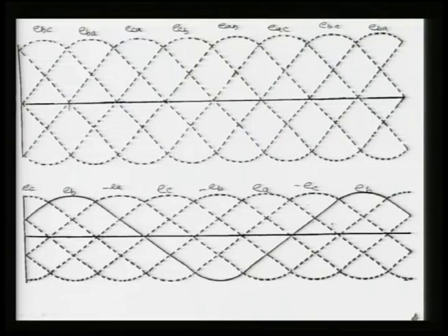Angles: I said alpha is 45 degrees, and here it is 60. So in between here it is 30, and then in between here it is 45 degrees. Here your valve 3 is getting a pulse. Now, after that you see the output voltage becomes 0. We are starting here; the output voltage is going to be 0 for 15 degrees, and the 15 is up to here.